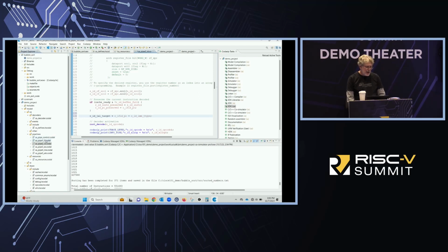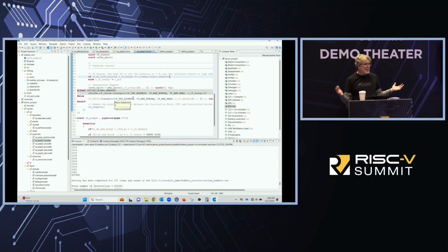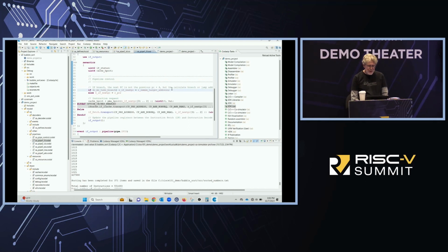So now I have to tell it that if I actually see something that's a JAL, to jump there. You can see I have this simple equation, and my first line is: if I have a branch, go to the branch target. Since a branch is decided in the memory stage, it's an earlier instruction than the JType in the decode stage, so I have to prioritize that.